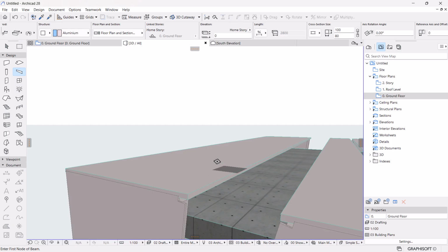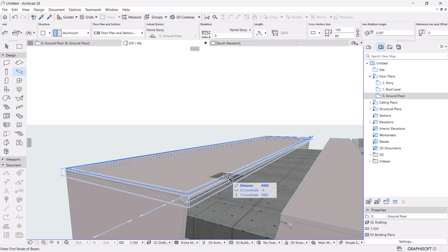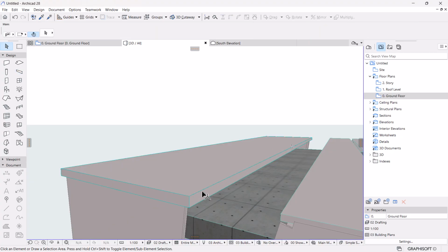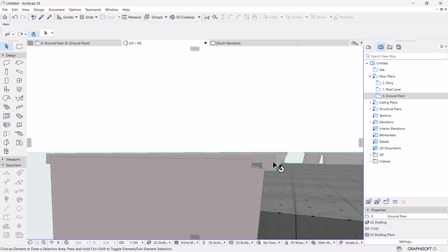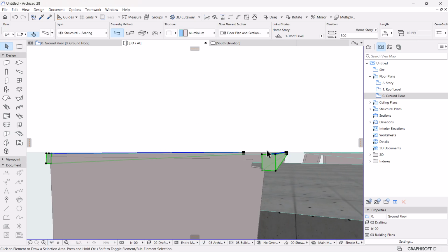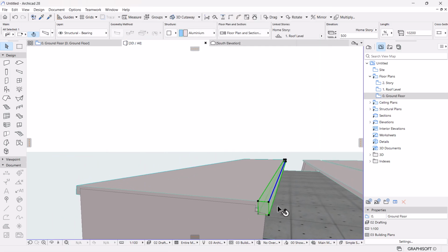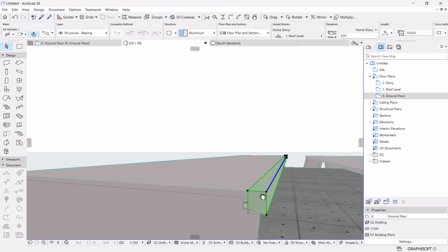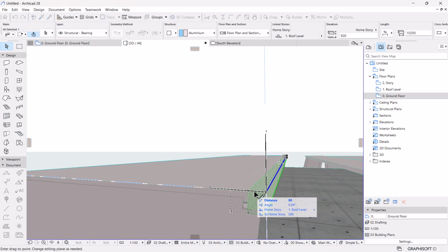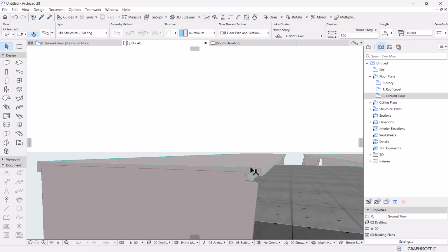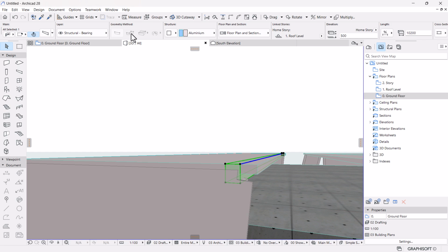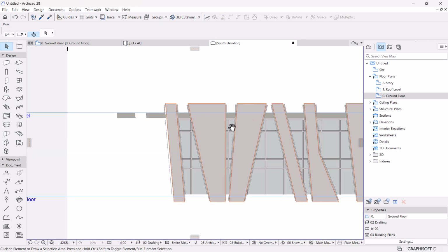So you could place this by pressing your spacebar key to activate the magic wand, and then click on the element like that. So you now have this one, we don't need it. So we now have this and that. Here we can set the axis to be on the inside. And the good part of this is you can control the depth as well, or align it with the top of the frame, and this should be done on the elevation.